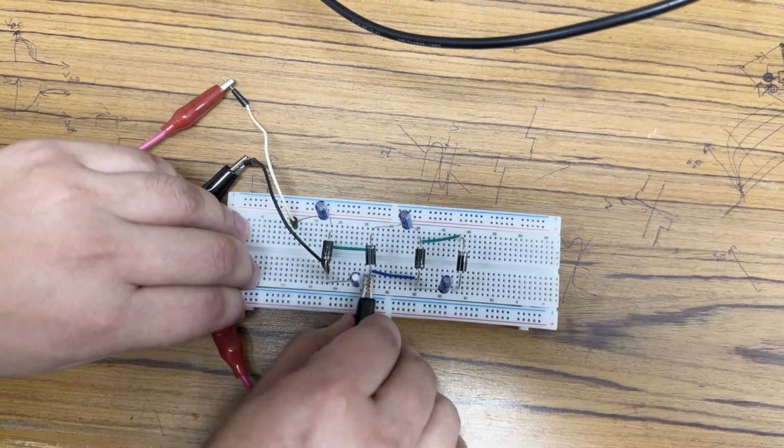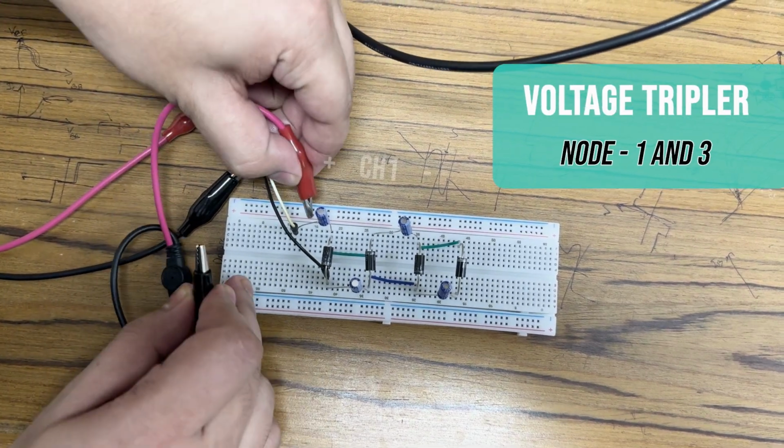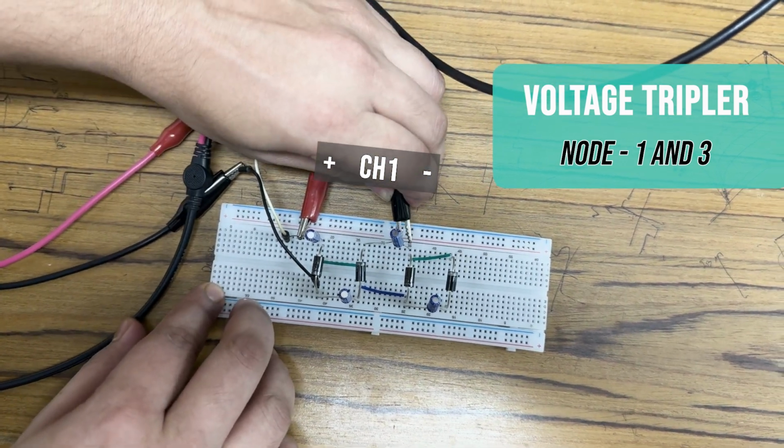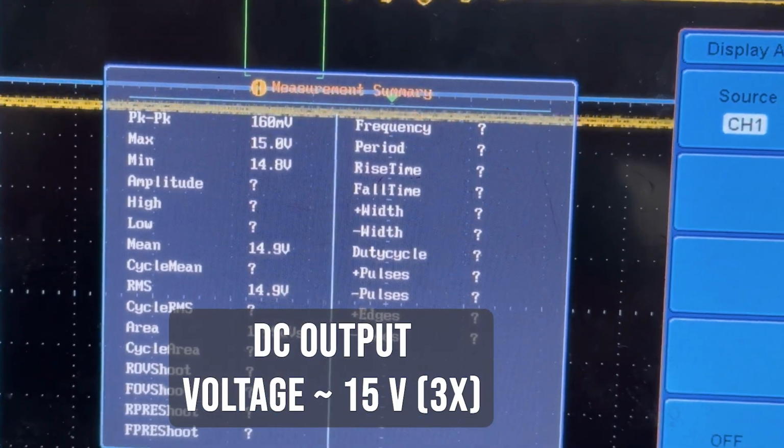Then to demonstrate the voltage tripler in effect, the oscilloscope channel 1 was connected across the first and third capacitor from the input side or across the node 1 and 3. The oscilloscope output shows that the input voltage has tripled along with being rectified.